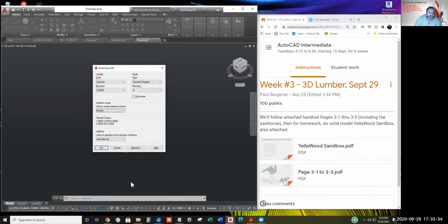And that way, if you mail order a sofa from Japan, and the dimensions are, I don't know, 85 millimeters. Is that realistic? No. 85 centimeters, 2 meters. Anyway, it's drawn in metric units. And your floor plan or your 3D house model is drawn with the assumption an AutoCAD unit is an inch or a foot.